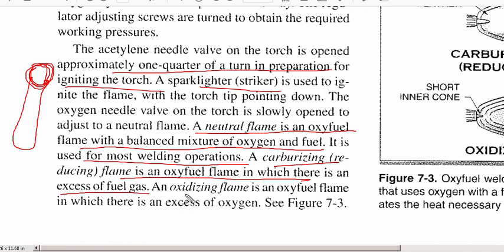And you can notice the difference when you look at the flame down at the base, really, in all honesty. Of course, video with this would be better as demonstration, but you'll be able to make the adjustments when you can see the levels, sort of the bluish nature of it. And you can tell the difference between excessive oxygen, too much oxygen, too little acetylene, and that kind of thing. Obviously, your neutral flame is what you're going for most welding applications.